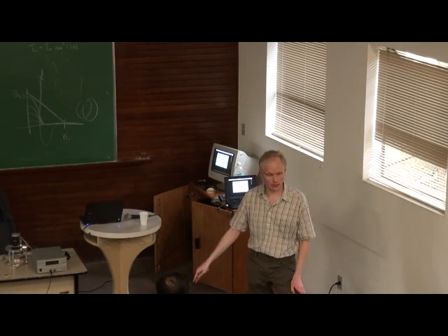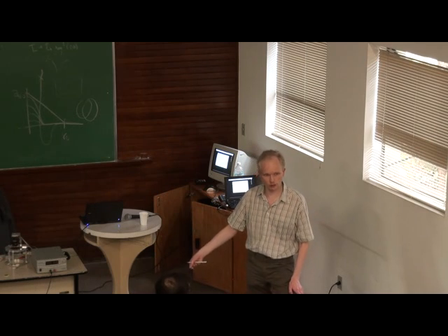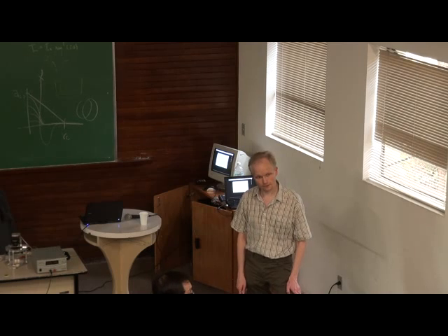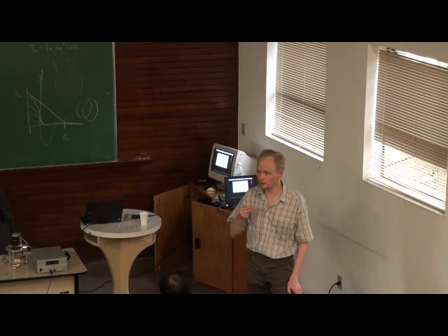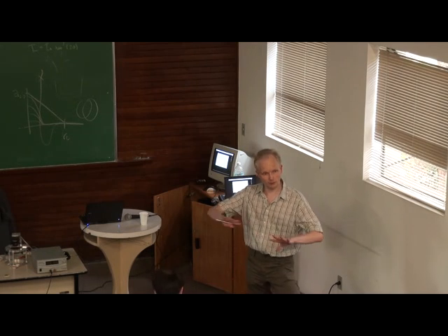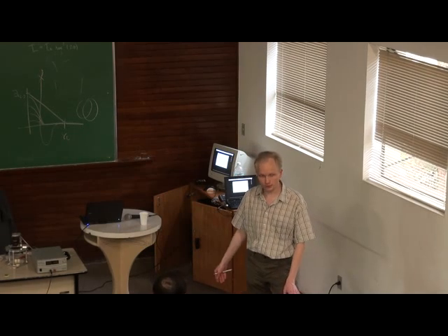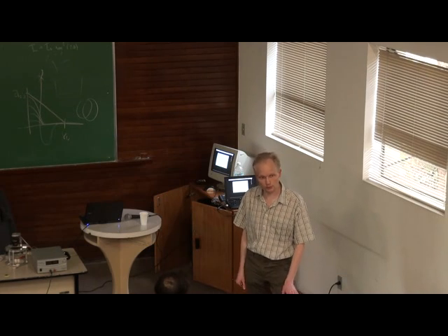There are many different bond potentials, angular potentials, dihedral potentials, pair interaction potentials to choose from. You select the equation and also put in the parameters. And of course, if you have many types, you have to specify all the cross terms also. If it doesn't exist, you can implement it yourself. It's not terribly complicated to add more interaction potentials.